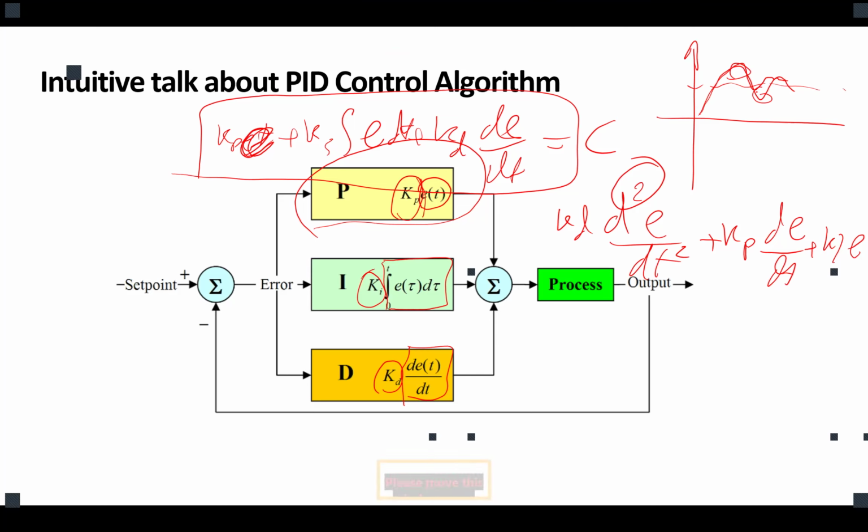They're going to oscillate around the set point until we get to it. How much we deviate from the set point in all of those overshoots and undershoots, how could we control them? By predicting the change and trying to damp them. So the derivative tries to smooth the process, lowering overshoot and undershoot by predicting the future. Are we good? So this is how it works.